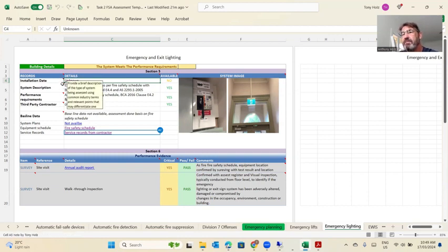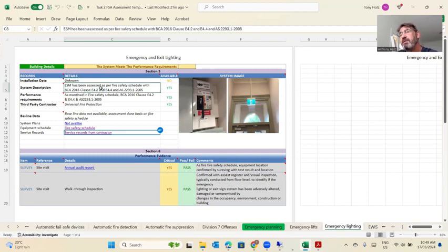That note down there really needs to be updated a bit so you can see the whole note. But essentially, it doesn't matter what system it is, whether it's a hydrant system or whatever. What type of hydrant system is it? Is it a pump system? Is it just a mains water push system? Does it have a booster valve on the front? So this really just needs to be a basic description of the system that you're inspecting and testing.